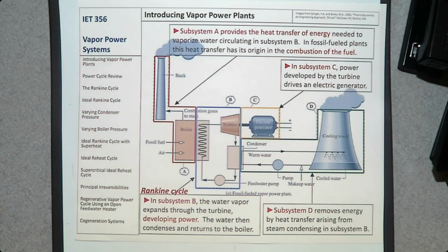The steam goes into the turbine, expands in the turbine to produce turbine work that is going to be connected to a generator to produce electricity, and any waste heat is going to be removed by a condenser which is connected to, let's say, a cooling tower or nearby river water, the lake or ocean to reject any waste heat. Once we reject the waste heat, we use a pump to pump this water back to the boiler to generate steam again, so it can be a cycle.